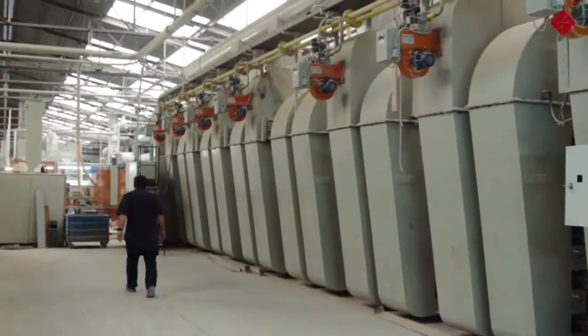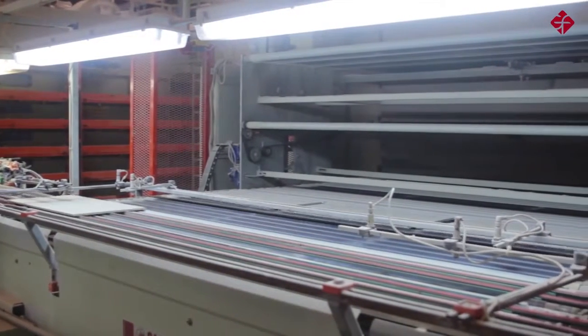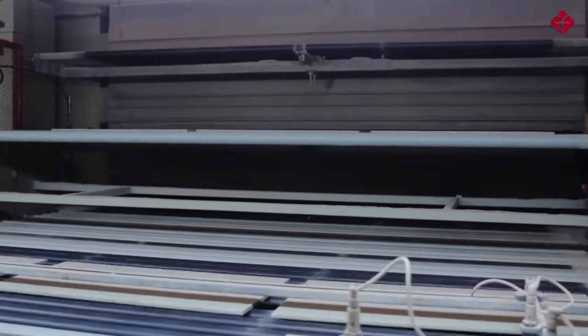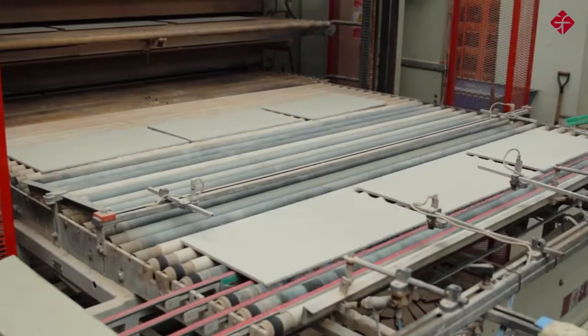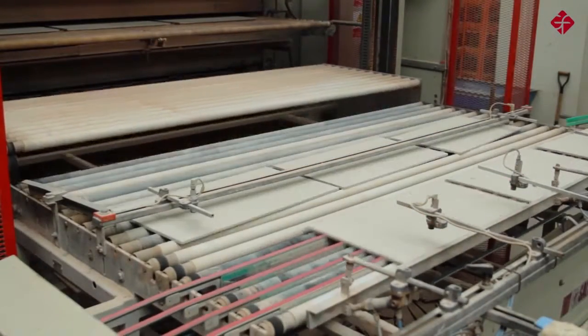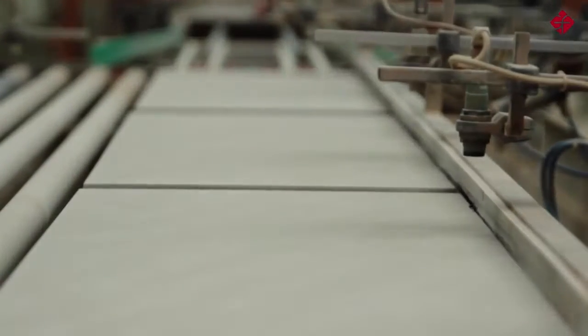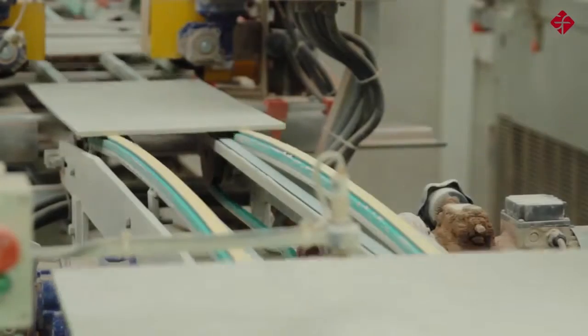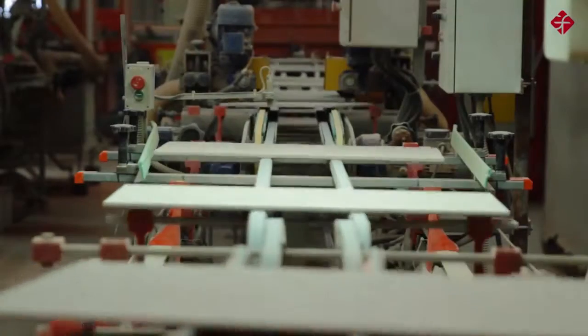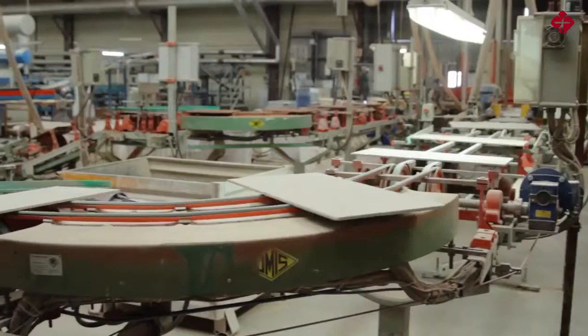The tiles are damp and must be dried. Drying is carried out in a horizontal dryer, and when the tiles emerge they have a residual humidity of around 0.5%. They are not dried anymore because when a ceramic tile is fully dried it becomes very fragile. Tiles have to be glazed and decorated. In other words, they are about to undergo a series of mechanical actions, and if they become too fragile they would run the risk of breaking very easily.